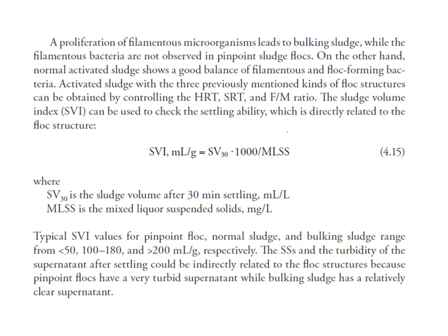As we have already studied, the settleability of microbial flock can be measured using SVI, which is sludge volume index. The way that we can measure is we just compare the volume of sludge in the beginning and after 30 minutes, and we compare the ratio of the volume, and by doing that we can see how easily this flock can be settled.